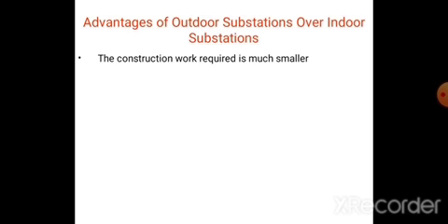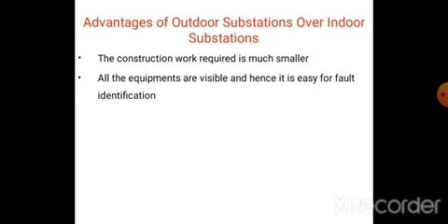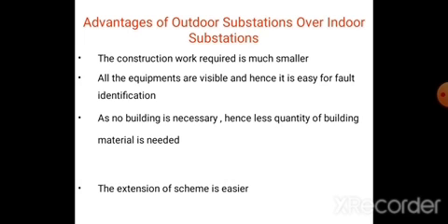What are the advantages of outdoor substations over indoor substations? The construction work required is much smaller. All the equipment is visible and it is easy for fault identification. The extension of the scheme is easier as no building is necessary, hence less quantity of building material is needed.